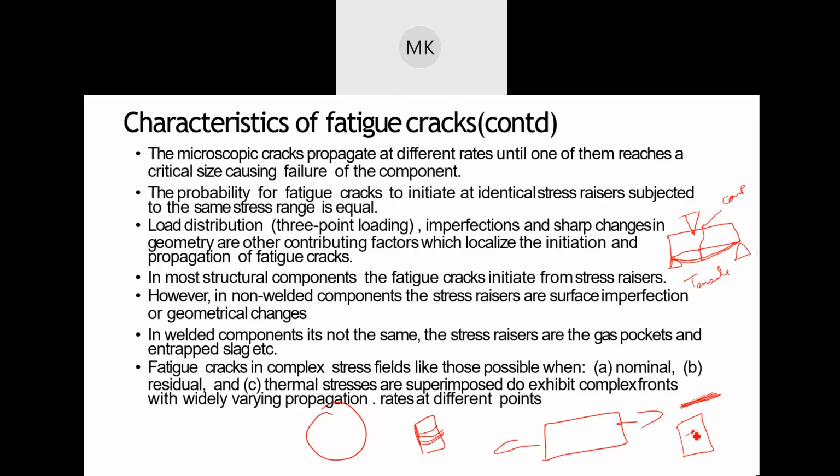Whatever the case is, I would have a big crack starting from that foreign particle or void in the material, that becoming the major crack and growing outwards. And this could be attributed to like 5% or 10% of the failures that happen in metals.